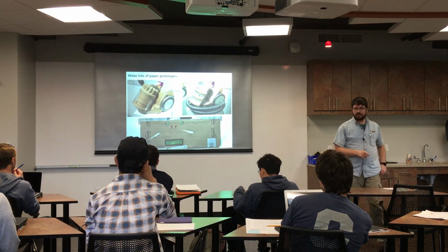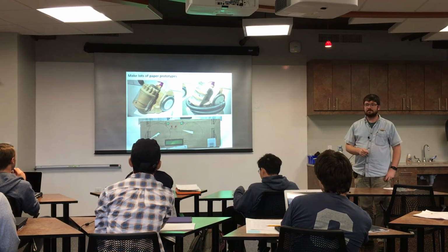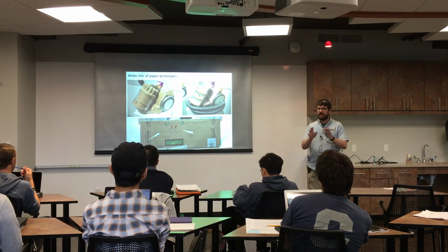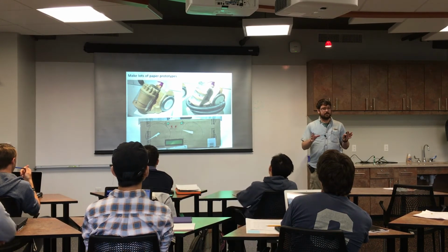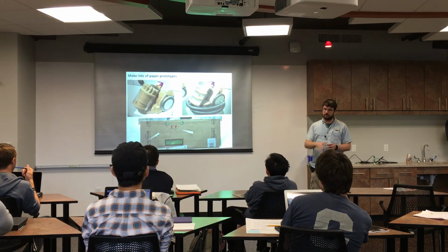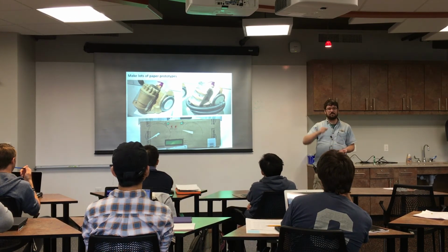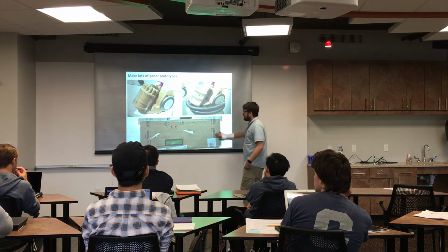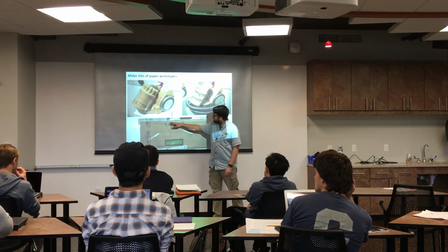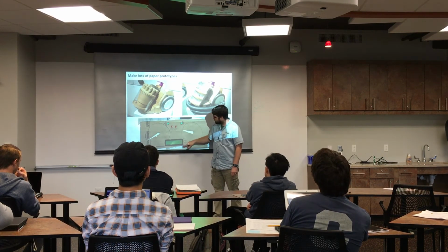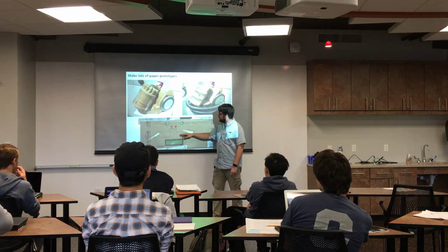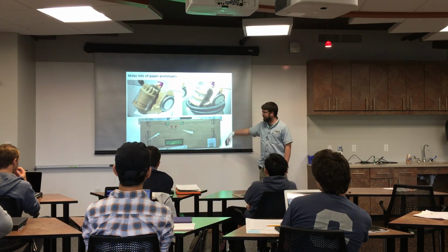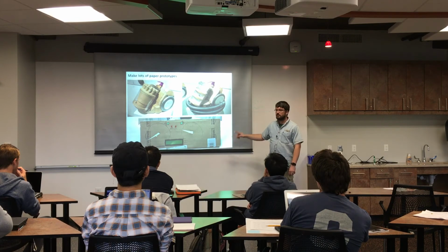Another thing that I would encourage you to do as you're doing your design is to make tons of what are called paper prototypes. These are not just toys. They're actually really useful design tools. You can print out on a 1-to-1 scale your design in Onshape, glue it to a piece of cardboard, cut it out, test fit things together, make sure that's what you want before you actually have the parts machined and cut. It could be something as simple as here somebody was mocking up a car dashboard. You can see there's turn signals, parking, low fuel, a little screen for the odometer and everything, and then 2 needles, probably a tachometer and a speedometer. So that's really simple. It's an Amazon box. So save cardboard, it's handy.